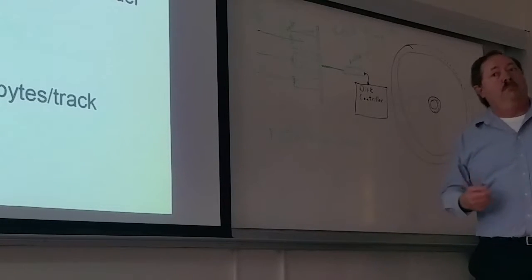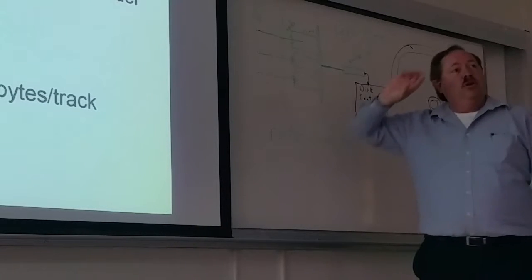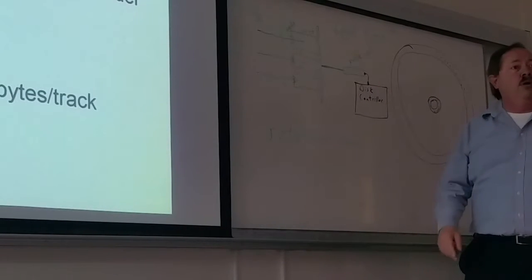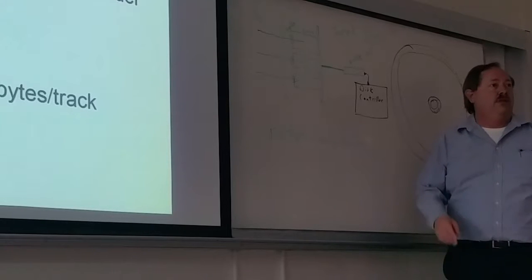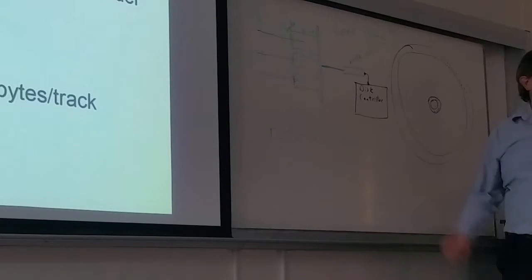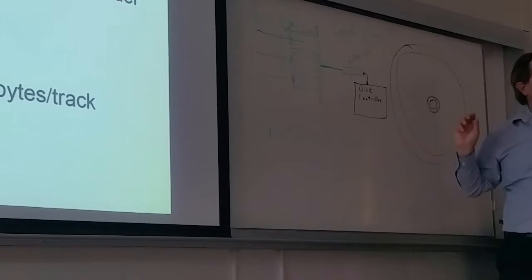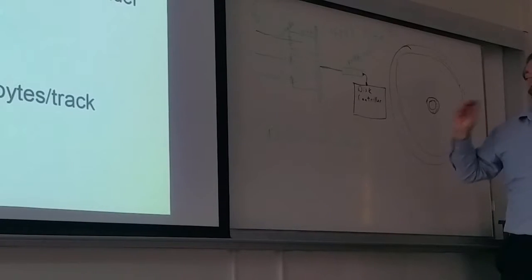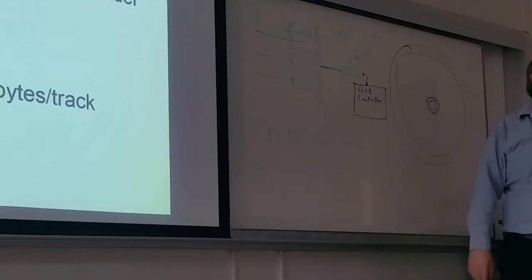It might take more, because we have found that sometimes when you're changing the spinning direction of that 1 or 0, it doesn't always fully happen. And so you have to do another write operation, and then you're going to read it again to make sure it worked. Once you've done that, then it's a successful write. You can go on to the next job.